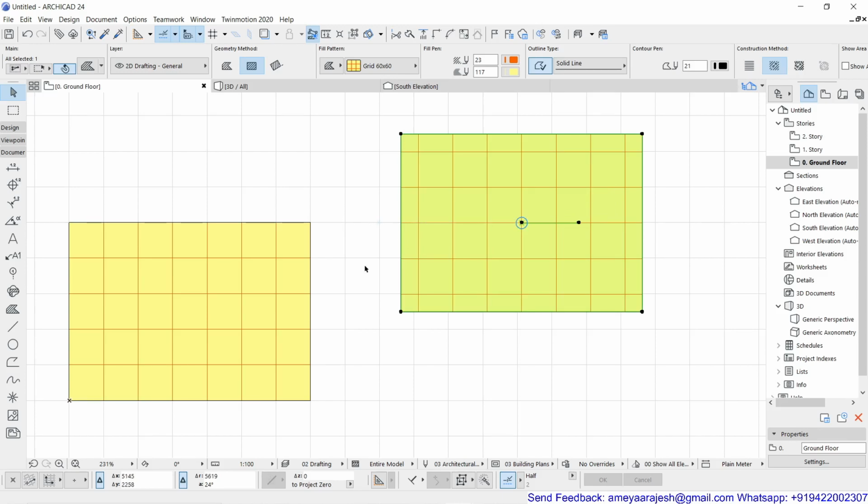Once you have achieved this change, you will notice that there's one vector added to the center of your hatch area. ArchiCAD will find out the center point of the hatched area or the field area you have drawn, depending on the shape. So don't worry if you have drawn a circle, hexagon, octagon or any odd shape. The maximum boundary or bounding box will be designed to your specified hatch, and then ArchiCAD will identify its center point, and at that point this vector will be placed.